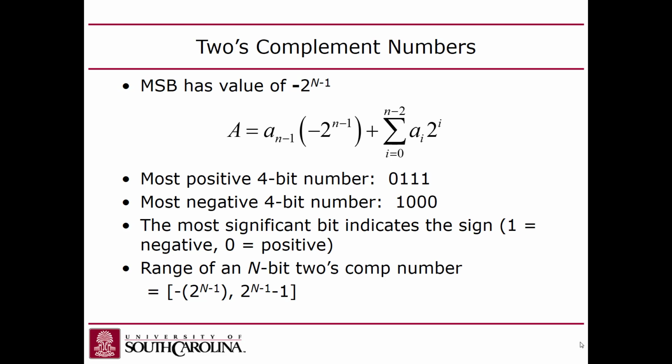So for instance, if we have two 4-bit numbers, let's say I want to add, well, first of all, what's the range of a 4-bit number in 2's complement? Well, if it's an unsigned 4-bit number, 0 would be the lower end of the limit. And then whatever value you want to represent would have to be greater than or equal to 0 and less than or equal to 2 to the n, minus 1, where the minus 1 is applied to the 2 to the n. So if it's a 4-bit number, 2 to the 4th power is 16, subtract 1 is 15, so we're 0 to 15.